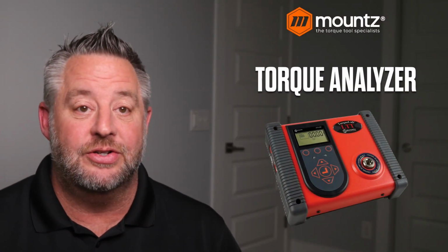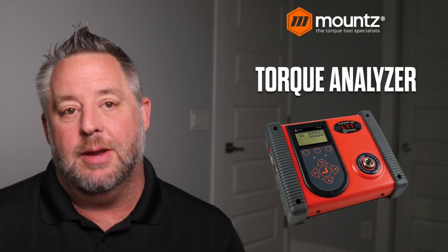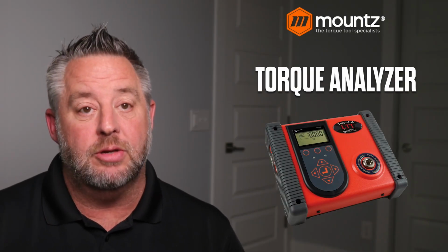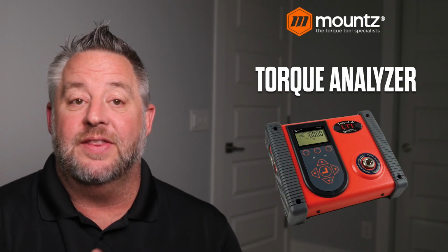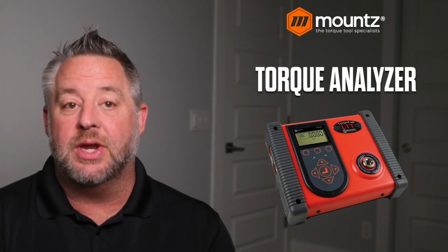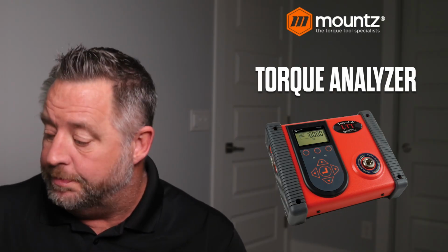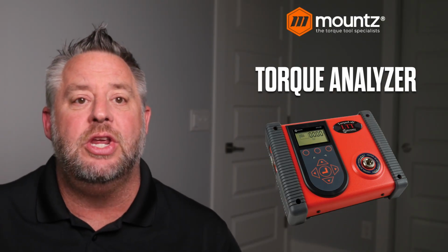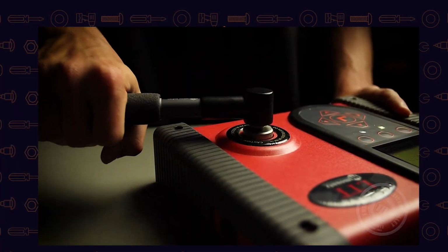Now, we also use torque analyzers to measure the amount of torque that a tool could be producing. And that is done by taking an analog signal and converting it to a digital signal, through the use of a strain gauge.